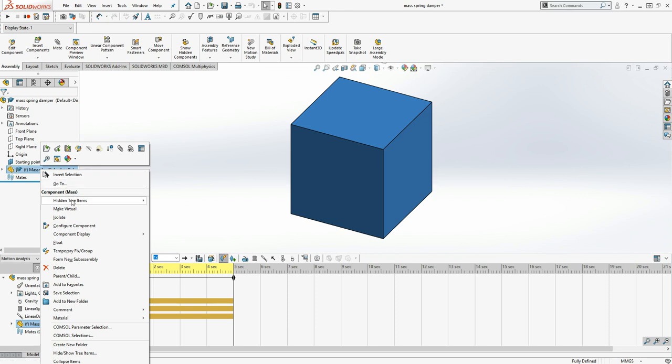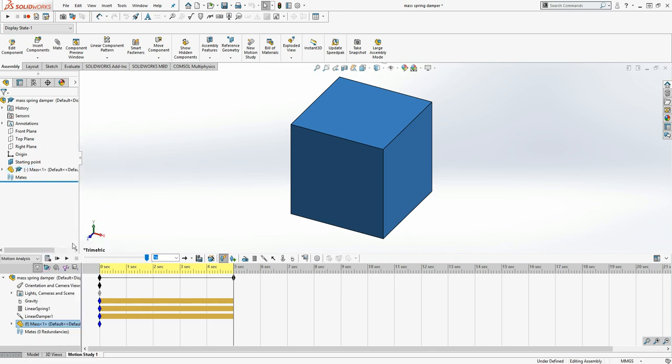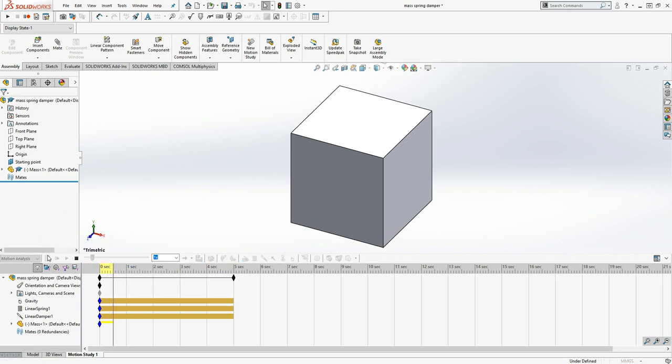If you go down the list, you'll come to float. It's because when it was brought in, it was set to fixed. So click float, and then let's try it again. You notice there was slight motion. This is where we need to tidy things up.